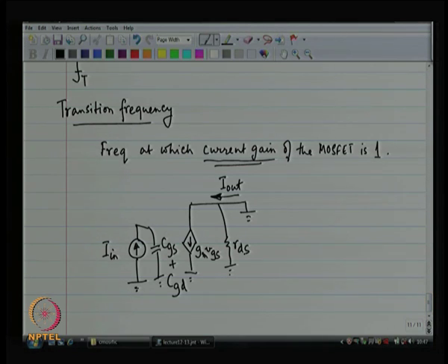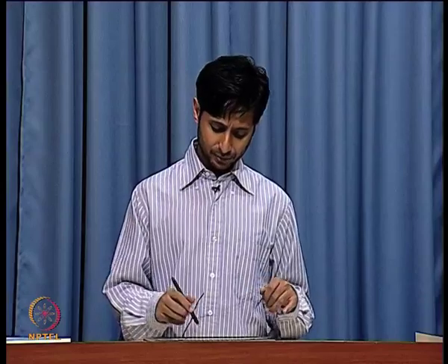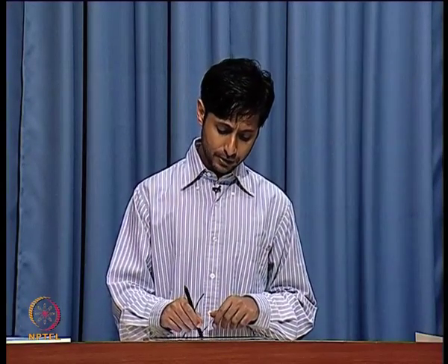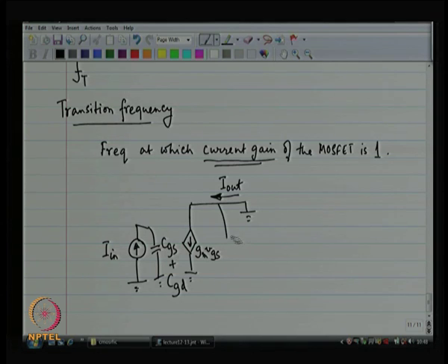I am throwing out the higher order effects like contact resistance and gate resistance and so forth. Let us not worry about those right now. Those will just add a few more terms here and there. Also the inductance does not really matter. What is going to happen to RDS? Both sides are at ground potential. So, no current is going to flow through RDS. Fine.